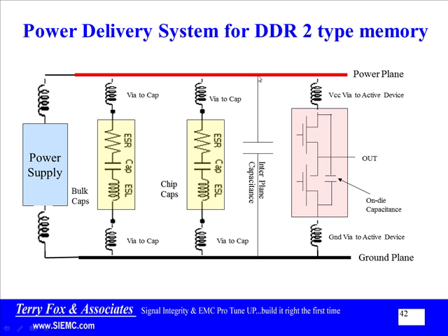And so consequently, as I go higher in frequency, this actually becomes more beneficial until finally we get to the point that the inductance associated with it starts becoming dominant, and at that point you'll find you go higher in frequency and it gets worse.